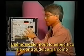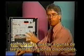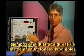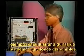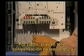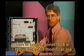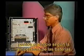Let's use this particular charge control model as an example to illustrate some of the other charge controller functions that you might have available to you. Certainly, you can have temperature compensation with a probe connected to the regulator to modify the set points based on battery temperature.